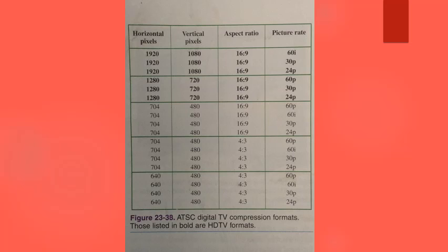There are some misleading terms used when describing advanced television systems. The fast evolution of these systems and terminology used by advertisers can often lead to disappointed customers. Enhanced definition television (EDTV) is a system that receives digital transmissions and displays images at 480p or higher. The fact that it can receive high definition transmissions and decode them makes it an enhanced system. However, actual HDTV displays images at 720p or 1080i.